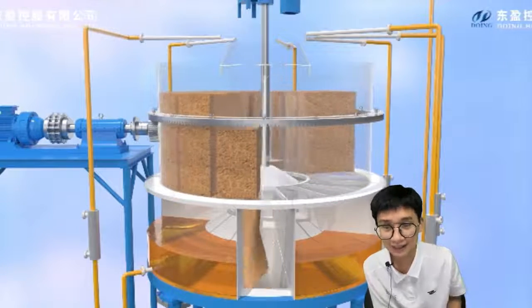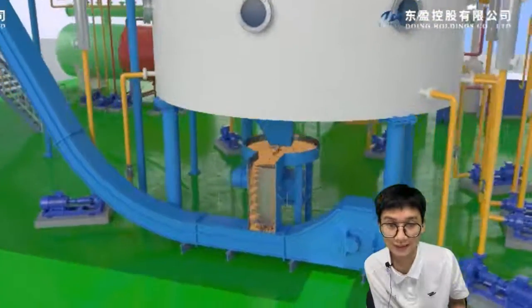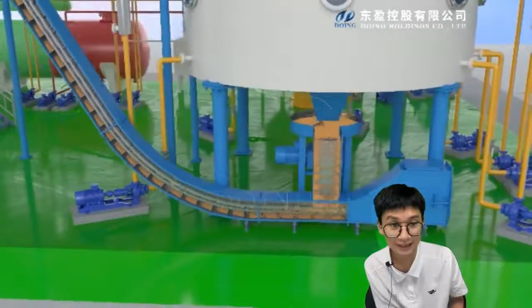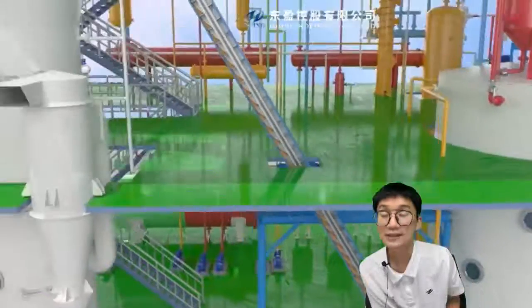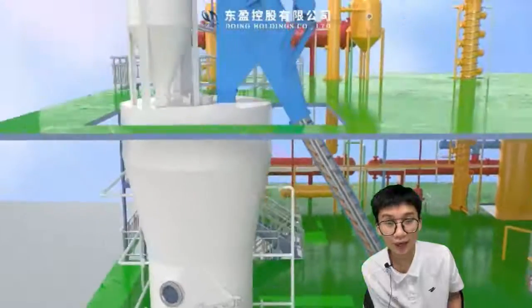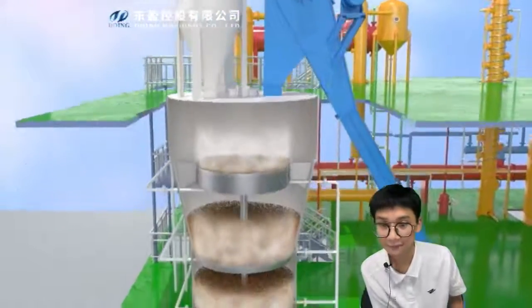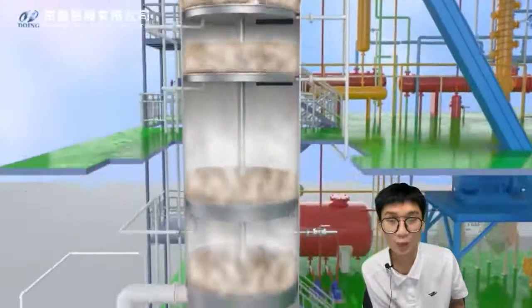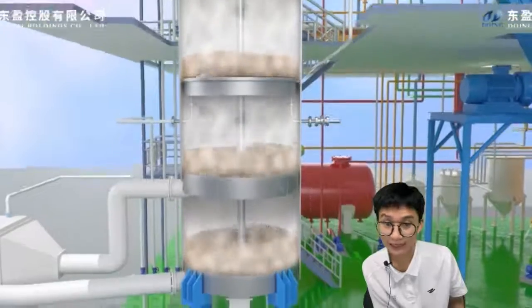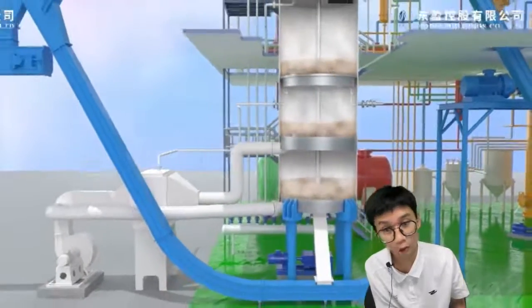And relatively, solvent extraction is more suitable for low oil content oilseeds like soybean and rice bran for input capacity above about 30 tons per day. As for high oil content oilseeds like peanuts, sunflower, and sesame for input capacity from 1 to 100 tons per day, it is better to press first, then choose whether to add solvent extraction or not.